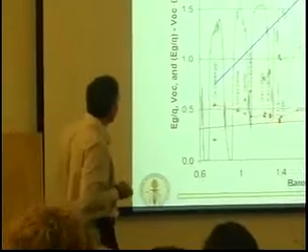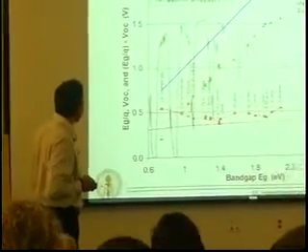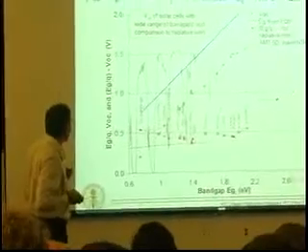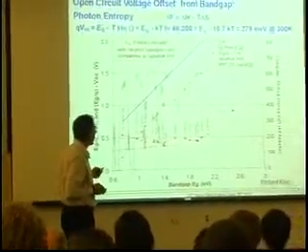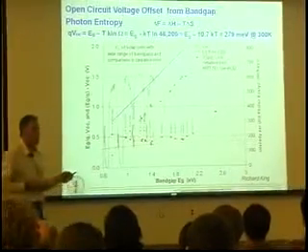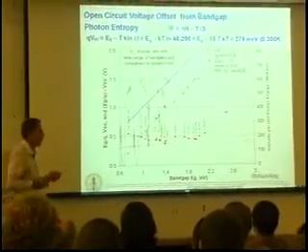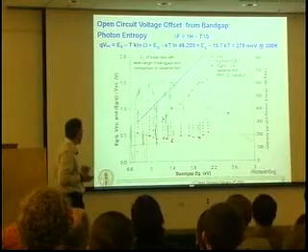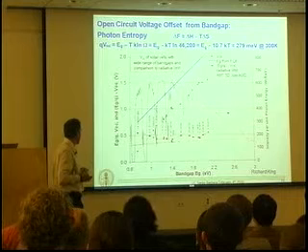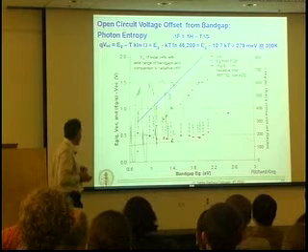So the open circuit voltage that's available to me is actually equal to the increase in the number of configurations of the emitted photon, which at room temperature is close to 300 millivolts. That's a significant energy loss of the incident photon that you can't do anything about because it's thermal as long as you have spontaneous emission. And that offset is well observed.